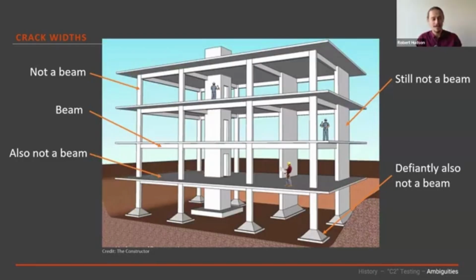It's probably actually overrating the capacity. Similarly, if you're expecting cracks less than that, then your capacity is going to be quite conservative. And one of the reasons we started playing around in the lab, trying to figure out how sensitive things like crack widths were to the end result, is because we wanted to understand how much this matters. And it's really sensitive. The outcome really matters on what your crack width is. And so it's a really important thing as a designer to be aware of, that when you use these values, that is what you're allowing for. And that's what's been tested.